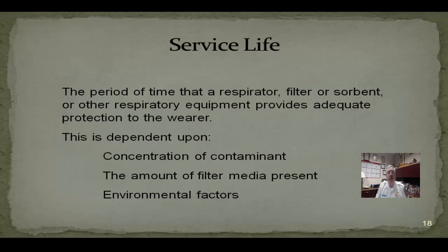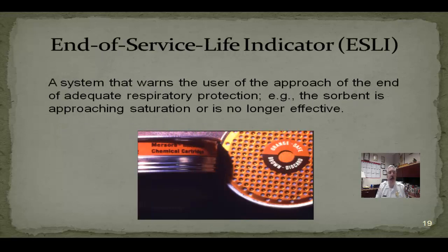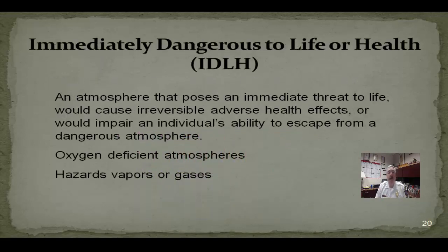Service life. This all depends upon how long you're using them, the amount of particulates that are in the air in the environment that's there, and the specific type of filter material that's there. Some have an end of service life indicator. These warn you of the approach of the end of the adequate air respirator because the absorbent is saturated with material, or it may be that its shelf life has gone to a point where the material is no longer capable of capturing the particulates that it's designed to do.